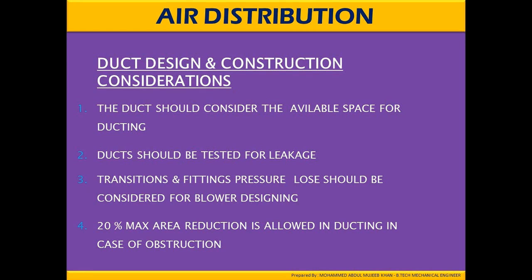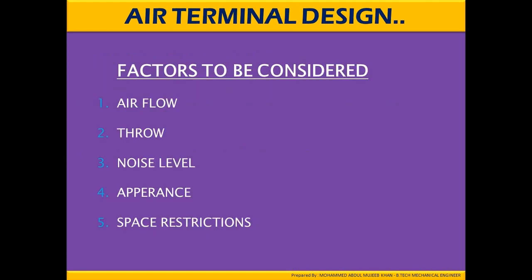Transitions and fitting pressure losses should be considered for blower design. 20% maximum area reduction is allowed in ducting in case of obstructions. Factors to be considered: airflow, throw, noise level, appearance, and space restrictions.